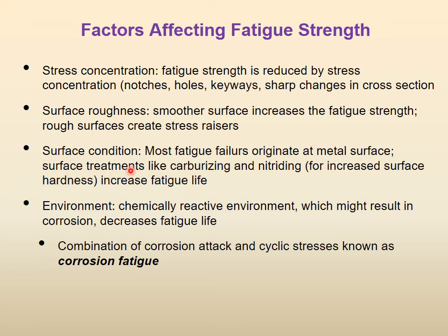Surface treatments like carburizing and nitriding can increase the surface hardness, so the fatigue life can be increased, right? So surface roughness, or the opposite of it, called surface finish. If the surface finish is good, the material has good fatigue strength. If there is surface roughness or the surface finish is bad, then the fatigue strength reduces. To improve that, you can do surface treatment.